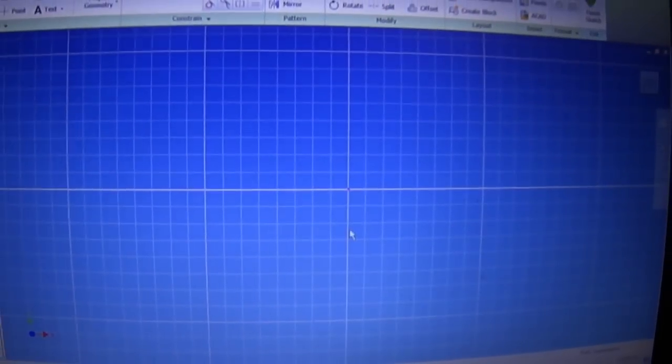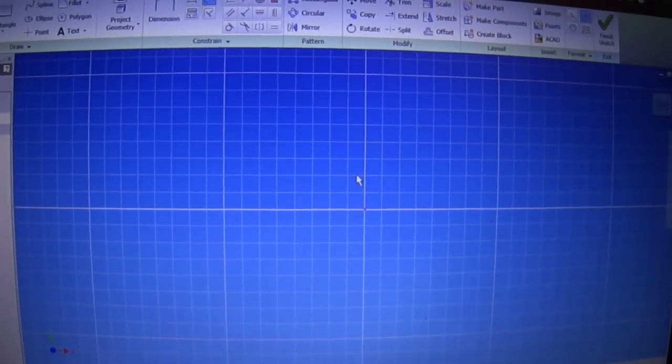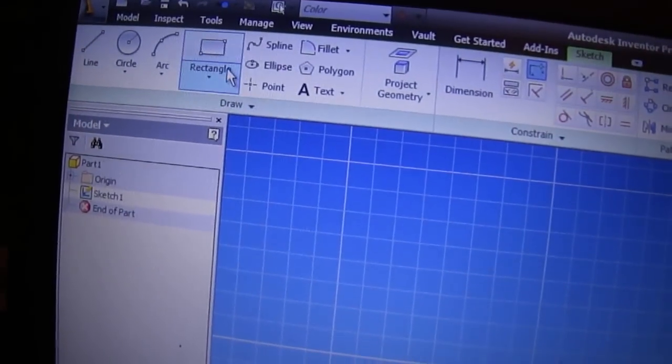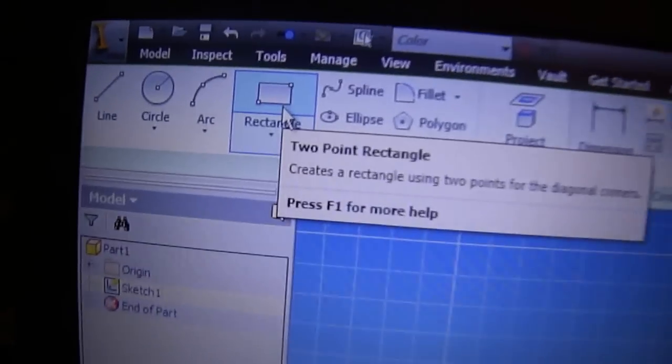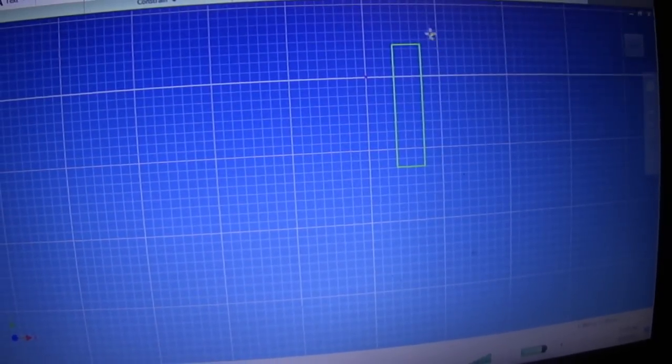So right now we are trying to create a hollow shaft using a revolve feature. So I'm gonna go ahead and select a rectangular feature on the top right here. Hit select, click anywhere from the center point on your graphic window, stretch your feature, click somewhere else down there, and now the other thing is to dimension it.